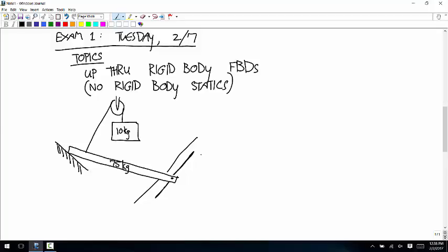So that means that for this system to stay static, we need this to give us 2 variables. Otherwise, we'd have 3 equations, 2 variables. And I mean, there are some cases where it would work out, but generally, you need 1 variable for every equation you have, or your system's overdetermined. So anyways, that's a long way of saying, if the problem didn't tell you what kind of joint this was, you probably want to treat it as a friction contact because you need 2 variables from this joint.